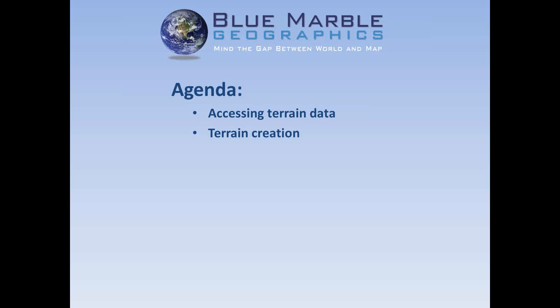We'll talk about creating terrain, transforming, I should say, perhaps a point cloud or some vector point data into a terrain model. We'll go through that gridding process in Global Mapper. One of the primary functions that people use terrain data for within Global Mapper is contour generation. Very simple procedure, very straightforward procedure. We'll show you that very quickly and how you can generate custom contours within the application.